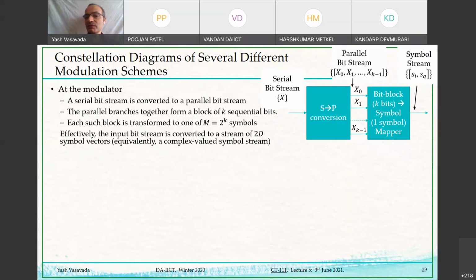We have seen what the bit to symbol mapper looks like for BPSK. It is nothing but 1 getting mapped to plus A, 0 getting mapped to minus A. We have also seen how this block looks for QPSK. From the constellation diagram of 8-ary PSK, we can also define what it will look like for 8 PSK. Basically, there will be 3 arrows here, 3 bits, and at the output we will generate in-phase and quadrature coefficients, or the coordinates. So this is the generalized diagram of a digital communication scheme.